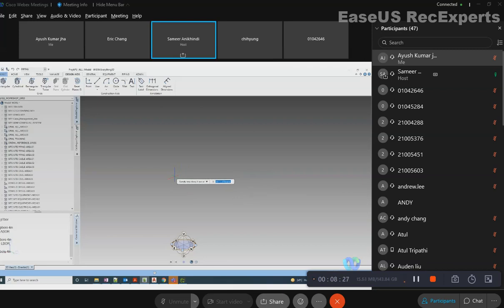In the x direction, let's say I will make from 0, 0, it will be, I think, 5 meter, then 2 meter, since my dimension units are meter, then 3 meter and so on. So once you are done, if you are not visible, you can right click and zoom extends.